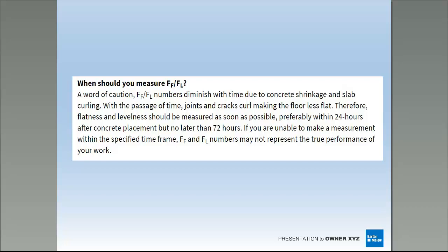When should you check FF and FL? This is a big point of mine, guys and gals, that I'm really passionate about. As a place finish guy, I'm judged within 24, no later than 72 hours, on how flat my floor is, because a lot of things happen with curl, as you can see right in this article or summary.